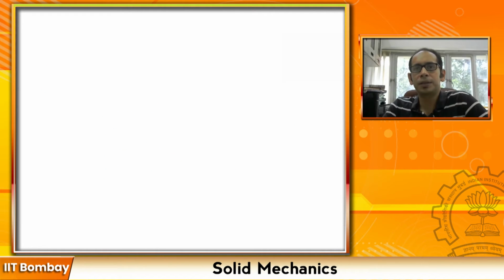So now that we have just started to scratch the surface of this particular topic on axially loaded members, and you have learned the formula that the deflection delta equals PL divided by AE, you are probably wondering that at most a complicated problem that I can give you is just a rod maybe fixed at one end, and if you're pulling with a load P, and if I give you the length of the rod, the area of cross section, the material it is made of to help you calculate the E, right? And eventually I will ask you just to calculate the delta, the deflection.